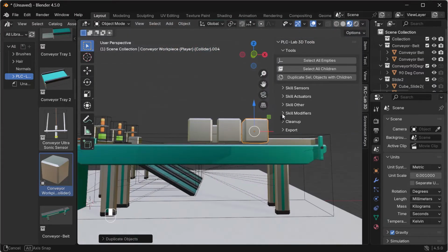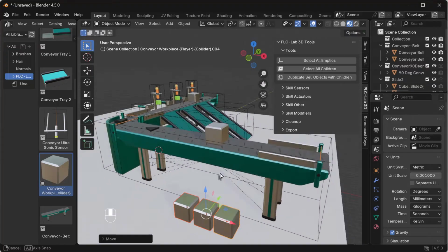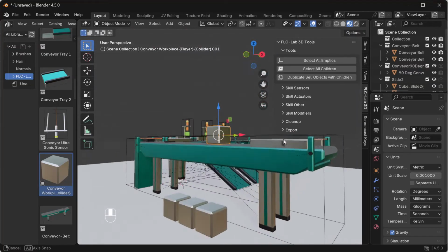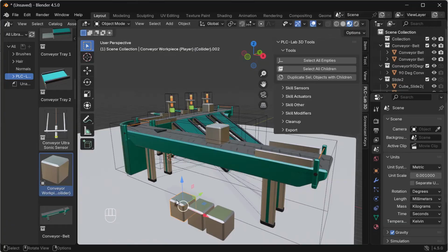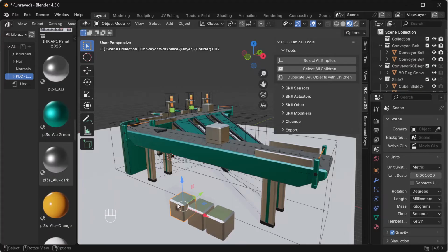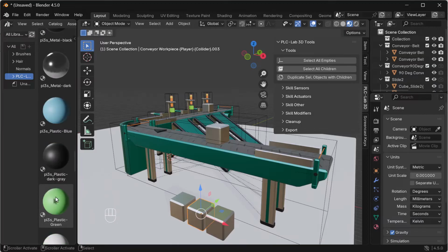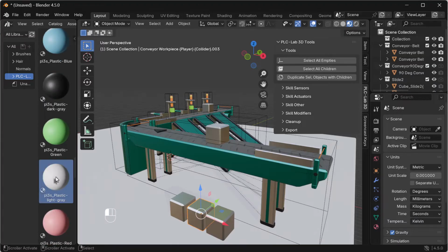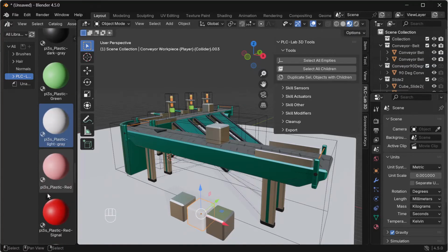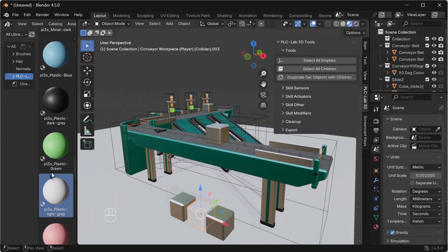Yes, of course. I'll continue building in the background and explain it to you briefly. Well, in a typical automation system, something is usually being processed. Whether it's a product or a bottling plant, something is being produced or processed in some way. This part has to be introduced into the system somehow, and that's the job of the creator. It creates objects. What objects can the creator create? Basically, any 3D object. You have to arrange the objects it's supposed to create as child objects of the creator. Then the creator knows what to produce. And the position of the creator is also the starting position of the children. So the cubes and the creator are placed.